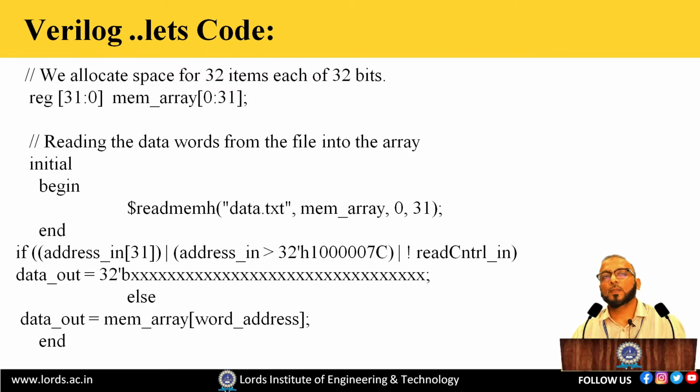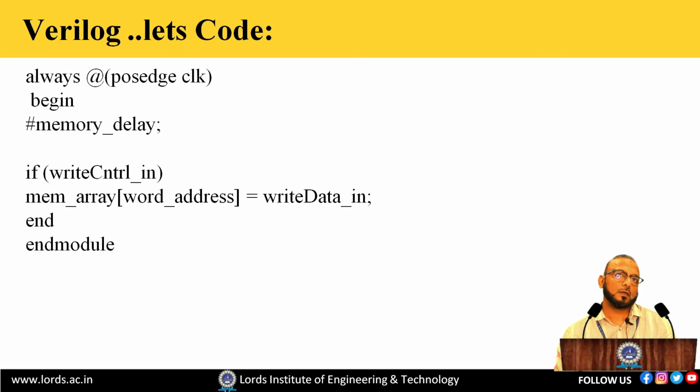To recall this, whenever you are using any statement synchronous with the clock, you have to write the positive edge of the clock. That means your clock works either on the positive edge or on the negative edge. So the main statement of Verilog is posedge clock, begin. Then I am writing a memory delay, as I showed you, a delay of 20. I didn't mention nanoseconds, but it's a delay of 20.